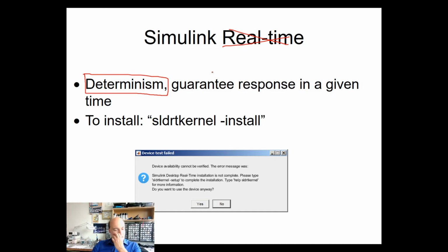And normally all those processes have very similar priority. But if you want to run a control application, the highest priority needs to be given to the control algorithm. So to sampling of the inputs, to calculation of the control action, and to the output of your data.